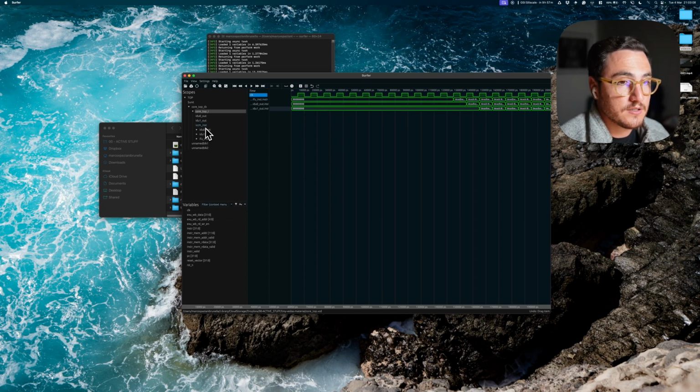In the next lecture, which is going to be extremely exciting because we're going to wrap up the ALU for this unit, we're going to get the compiler for RISC-V, we're going to attach the golden reference model, which is Whisper, and we're going to modify the testbench a little bit to generate a log of the instructions that get executed. And we're going to compare the golden reference with our core, and we're going to see if we made some mistakes or not. And we will start running our first ever program on this thing. So this is like the heartbeat test, to see if this thing is alive or not. So tune in for the next lecture. It's going to be extremely exciting.